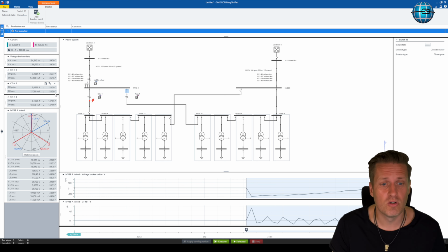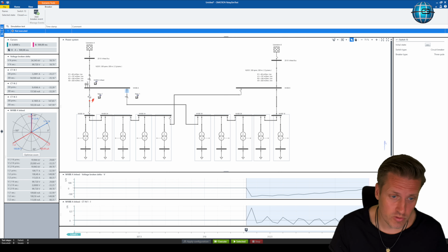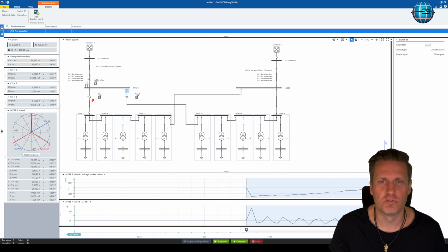And this is just because all these capacities here are just now added to this measurement point, because all these capacities also flow back via this ground fault point through our current transformer, but they only flow one time through the current.